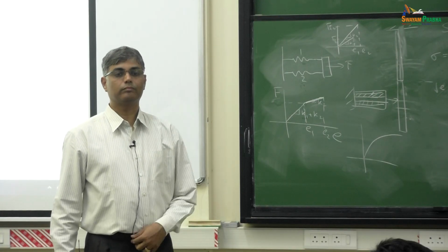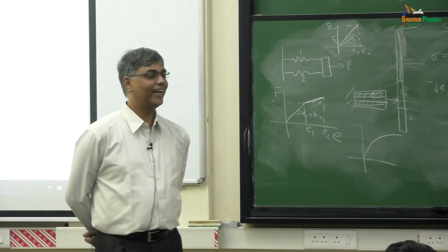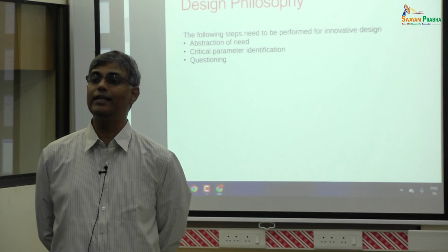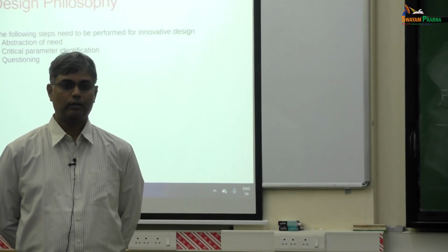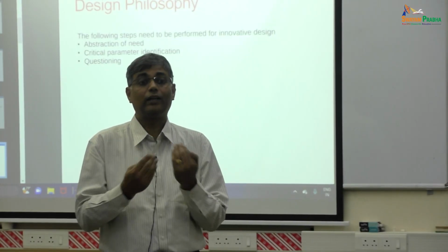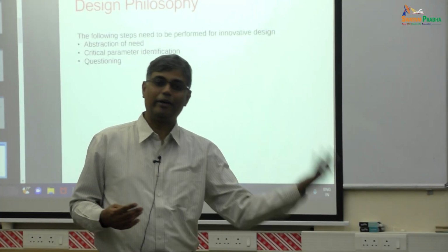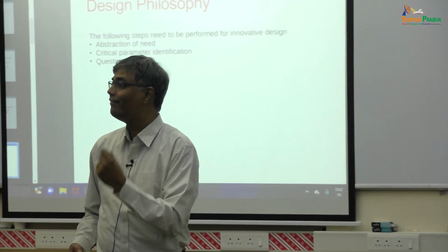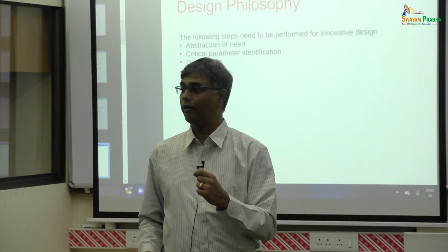While we can imagine the object as multiple springs, how do we calculate the K value of each spring? Excellent question. So this is a model, and by the way, this is true with all models. You can only conceptualize the model, but there will be some properties that depend on the actual material. If this is made of glass, you would expect K1 and K2 to be some value. Made of rubber, you'll have different K1 and K2. If it's steel, it'll be different, right? So I have to have a systematic way by which I can calculate K1 and K2.